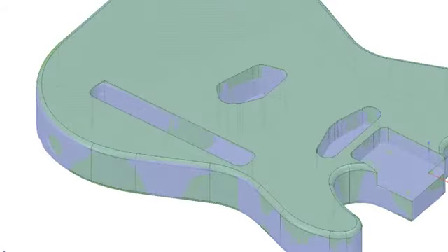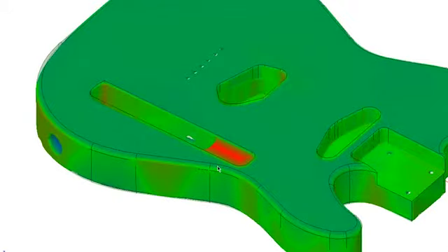And it'll calculate. It'll just take a second on screen. But yes, you can do a 3D deviation between the two and understand maybe where I made a change. As you see on screen here, it may take a second to update. There's a red area where I dragged the pocket. And I can change a lot of the settings in this dialog. But that just shows you that the tool does exist. There is a deviation tool in there to make sure that you're within a certain tolerance or to make sure that you got everything.